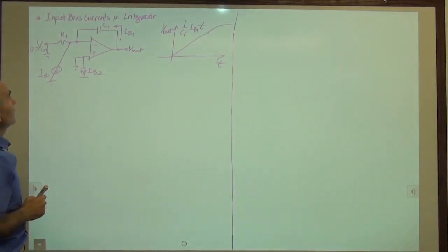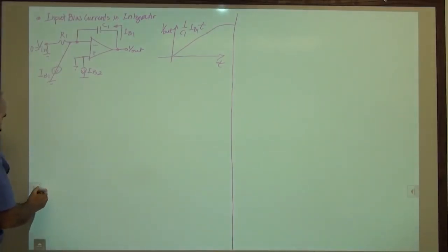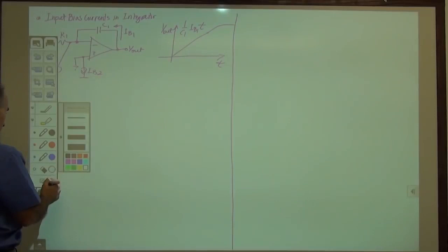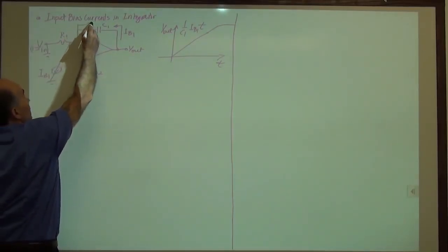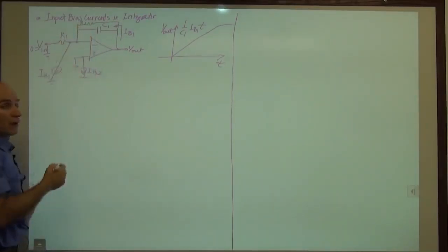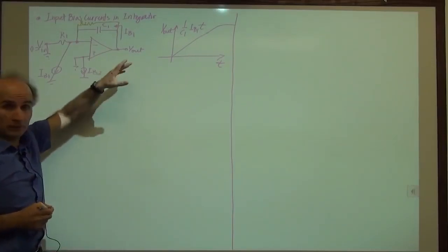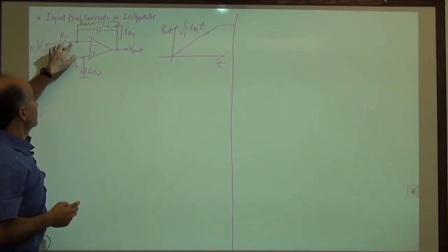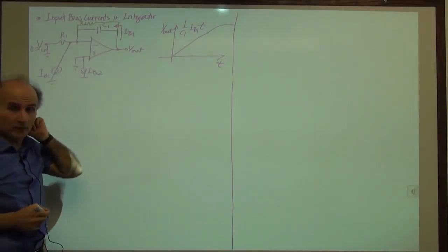A partial remedy is to add that resistor there. Remember that resistor that we put here? That's really the only reliable solution that ensures that the circuit does not saturate. It forces any currents that we need to draw from here to flow from R2, not from C1.